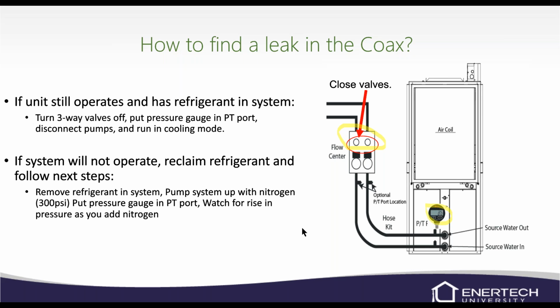But basically you're just going to, again, put the pressure gauge in there, pump it up with nitrogen and see if it pushes nitrogen into your water. It'll go up pretty quickly. It's a real quick way to know. Don't just say, well, I've looked over the whole system and I can't find it anywhere else, so it has to be in the heat exchanger.